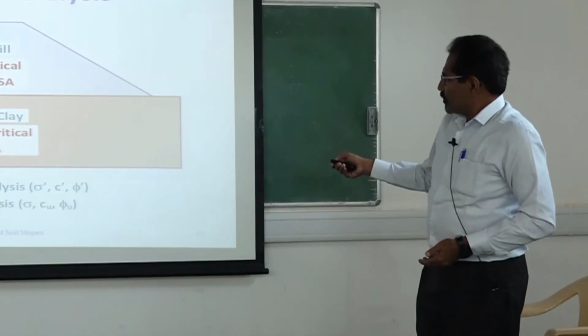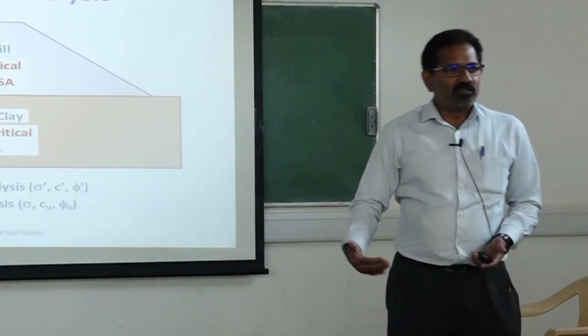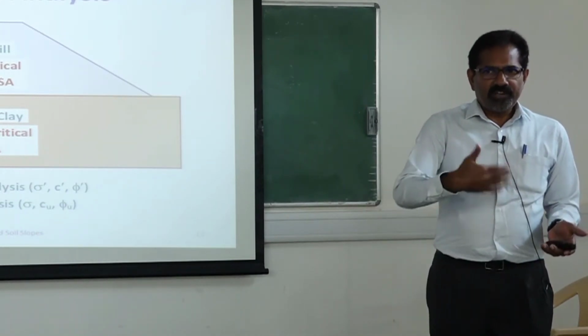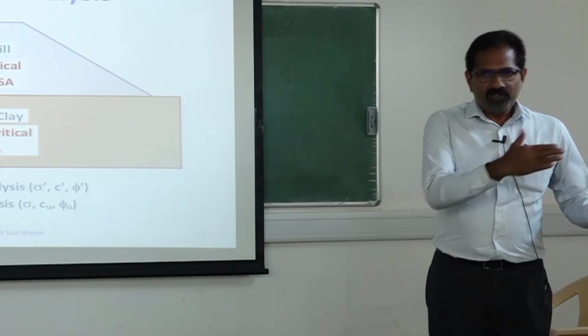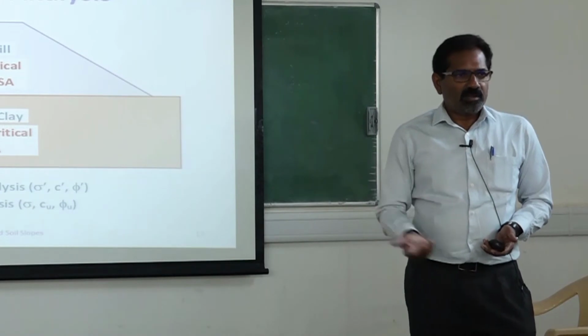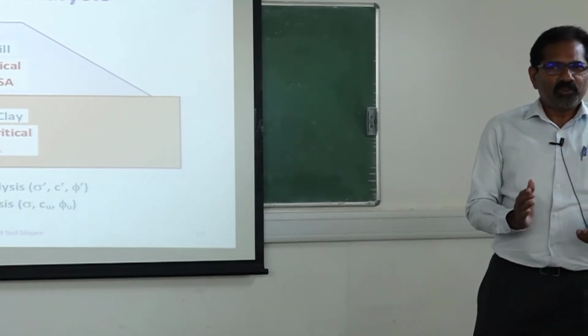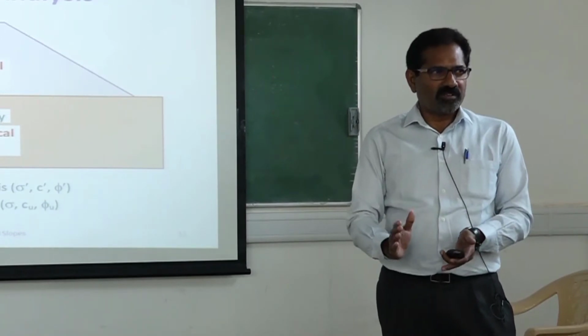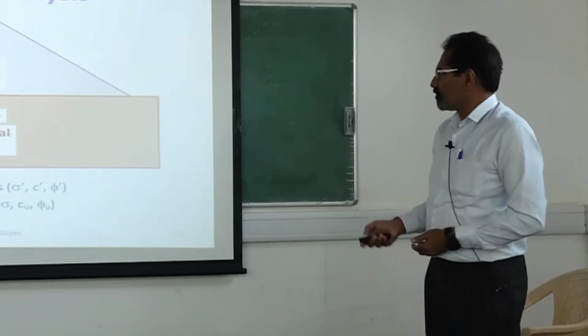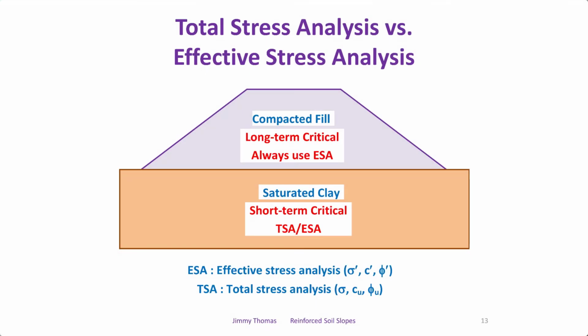And wherever short term is critical, we can do any approach. We can do the total stress approach, because short term is critical. So that we are taking care of with the total stress approach. And anyway, we know with time the factor of safety will increase. Or we can do effective stress. Both are equally applicable. Because sometimes, see, if you want to do the effective stress, we should know the pore pressure. Whereas total stress is easier. So that is why it's more convenient like that. But if I do a total stress analysis for a long-term case, then initially I'll get a higher factor of safety, but after a period of time, that is going to reduce.